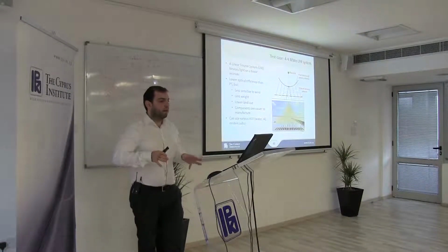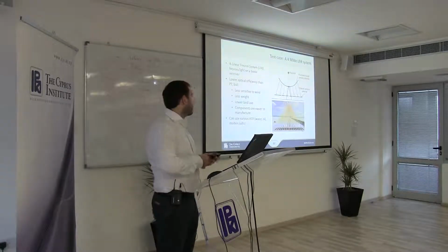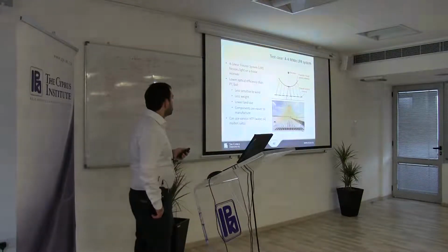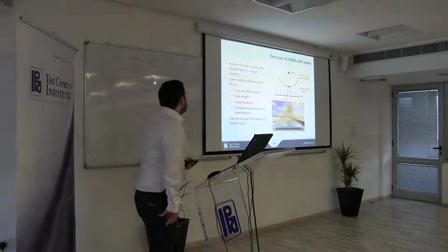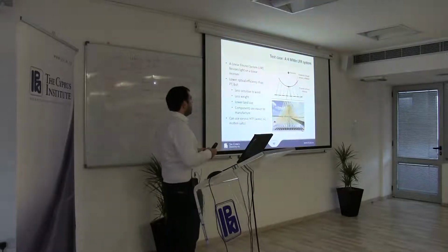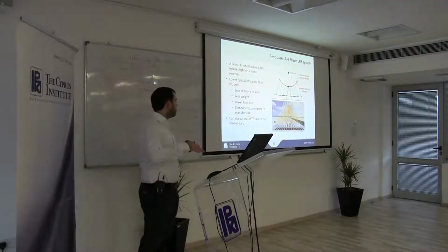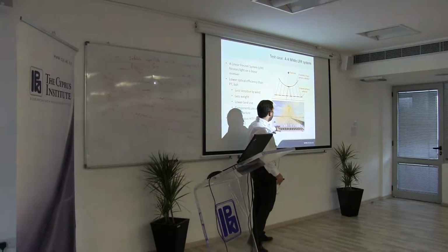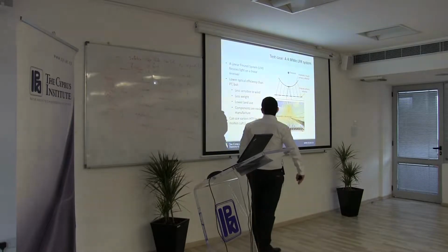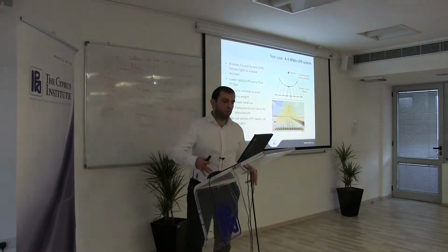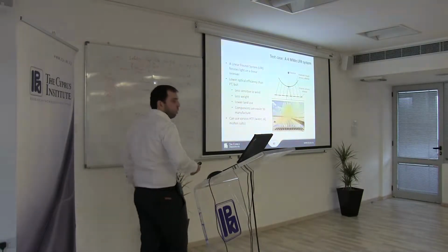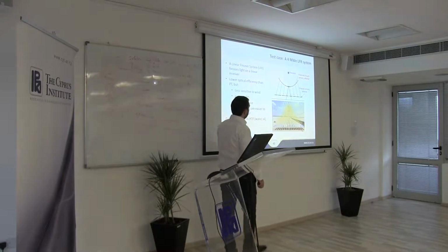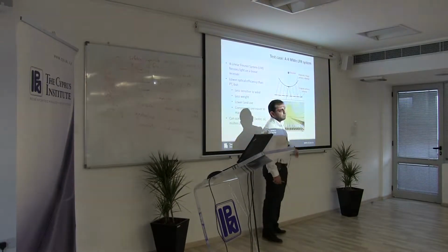If we look at some of these concepts in the context of a particular example, a test case of a 4 megawatt electric linear Fresnel system was built in SAM, the System Advisor Model of NREL. The linear Fresnel system focuses light on a linear receiver, as you know here. It has a lower optical efficiency as light can bounce off outside the receiver area. But it's less sensitive to wind because of its shape. It has less weight. It uses a lower amount of land. And the components are easier to manufacture, especially because they're flat and not curved as in the case of parabolic troughs.